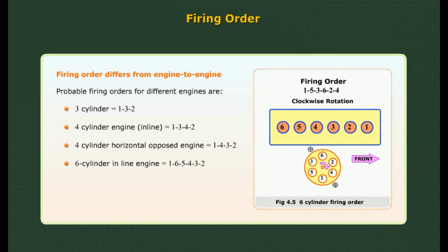6-cylinder inline engine 1, 6, 5, 4, 3, 2. 8-cylinder inline engine 1, 6, 2, 5, 8, 3, 7, 4. 8-cylinder V-type 1, 5, 4, 8, 6, 3, 7, 2.